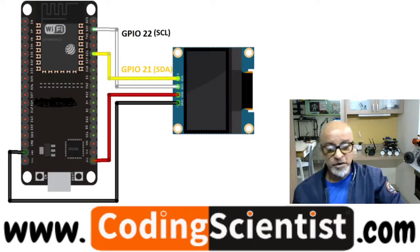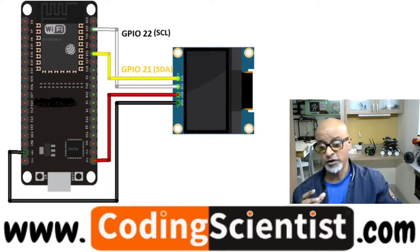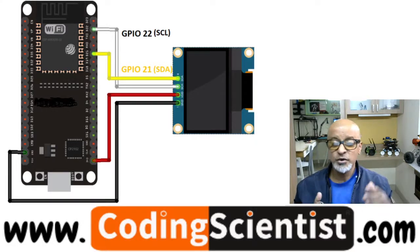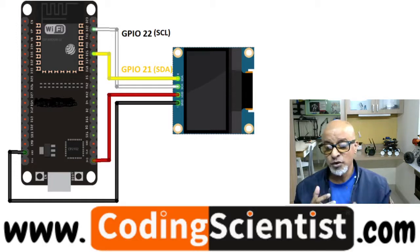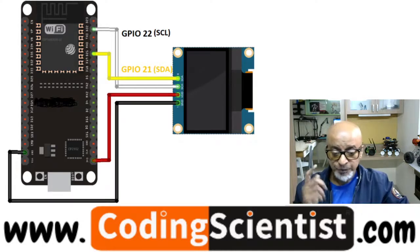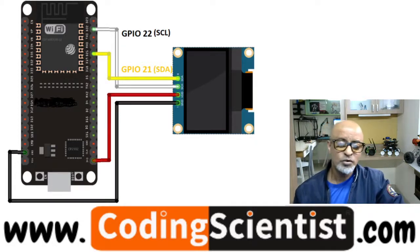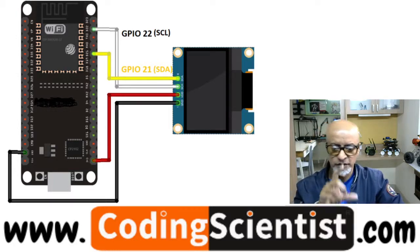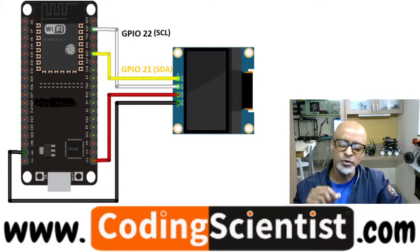But before doing that, we need to read the I2C connection, right? It's very important. You need to read which I2C address is being detected by your ESP32, which is connected to your OLED device. In order to do that, you will have to go to my GitHub account. I will show you in a minute, and then I'll show you how to copy that particular section of the code and load it into the ESP32 to read the I2C connection.